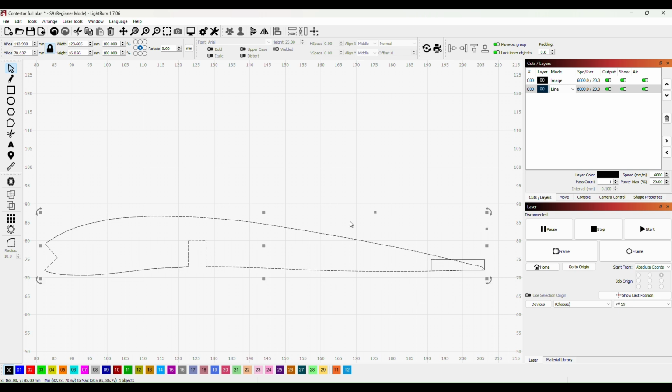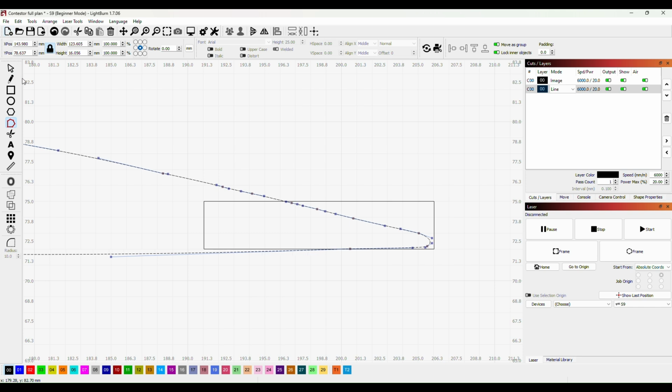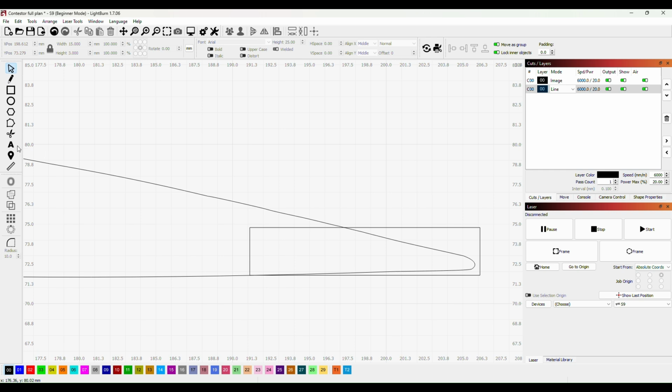of the aircraft. So if we go back to node mode on here, what I want to do now is shape this trailing edge. Now let me just move that down a little bit, because I want the bottom there to be relatively smooth. Transition there, just like that. Okay, so if I go back to nodes and then select our path, I want to insert a node right on that corner. So I'll insert, click, make it a corner node, press C, and then I want this node here to finish right on that line.